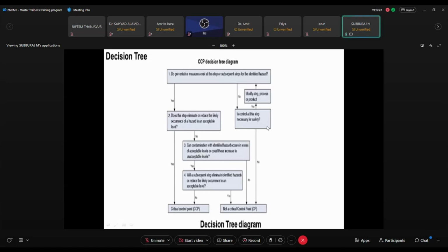That is also known as flash pasteurization. You have heard the name flash pasteurization. Sometimes 138 degrees for 2 seconds. Nowadays, since we are all busy, generally the companies set 138 degrees for 2 seconds, in others 89 degrees for 1 second. Like that, the companies may set it according to the requirement or the demand. Okay.